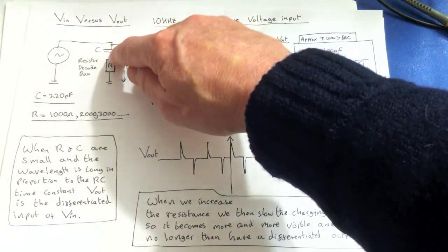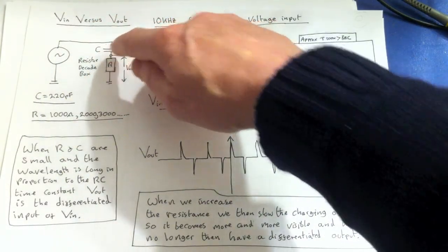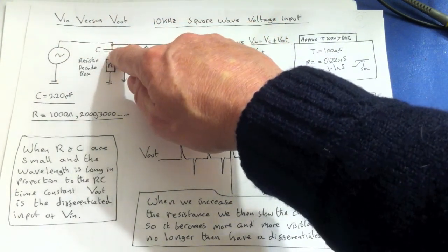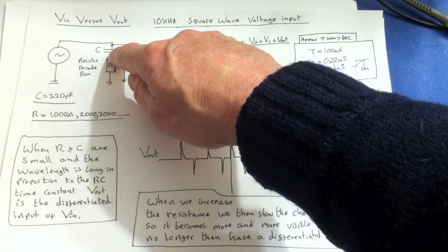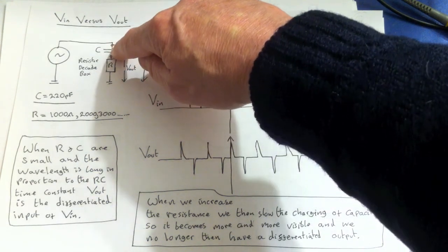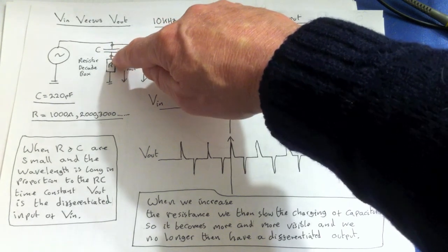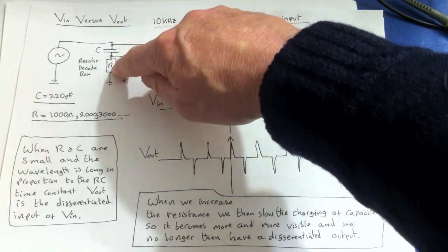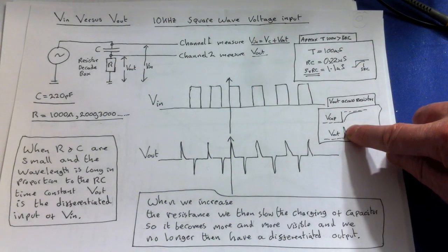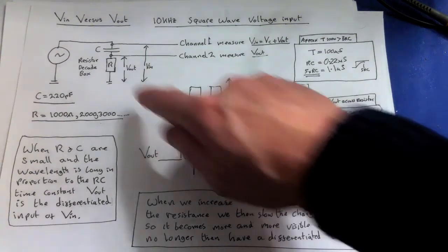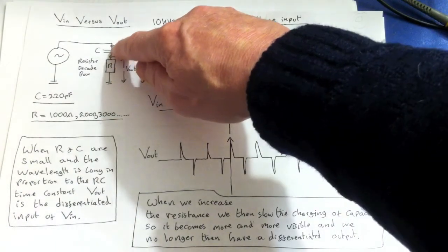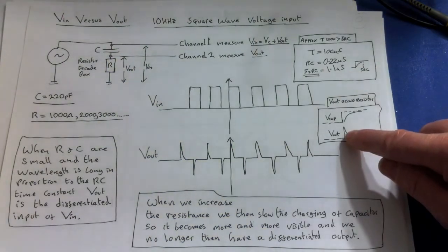So obviously the current then is flowing at its fastest rate. Because it's flowing at its fastest rate, and we effectively have no charge accumulated on the capacitor, that is basically a short circuit. So all of your voltage at that moment in time is going to be dropped across this resistor. So hence you get this sharp peak in this little box here. So across the resistor, at the very first instant, when there's effectively a short, you get a spike.